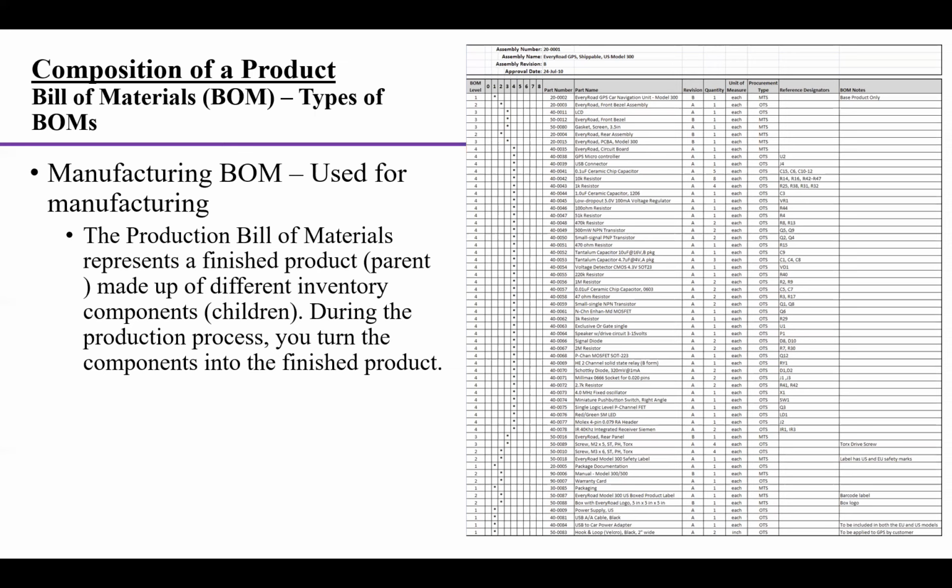So this information should be pretty clear, illustrated in the BOM. And you can see from this example that it includes all the relevant information. Sometimes you can also add a note related to how to assemble it in the workstation. So the idea is this BOM is used by manufacturing engineers to organize the production data, for example, the inventory.